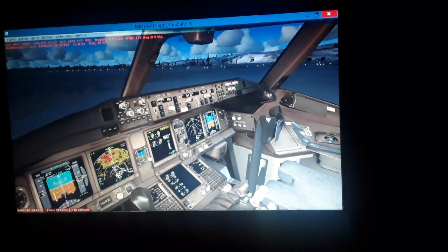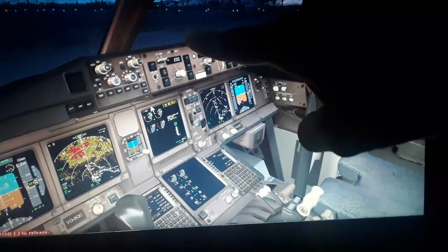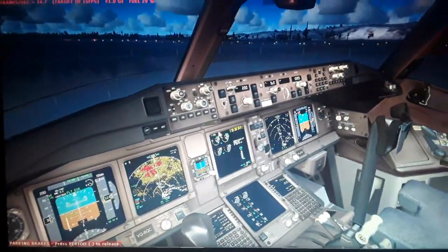Also, this is gonna give the data to the autopilot flight director system panel for the LNAV and the VNAV functions of the autopilot and flight director system panel. You can see here these two switches take all the data from the flight management computer for flying the aircraft in the automatic mode, using this data for the later vertical navigation of the aircraft. We're gonna follow this purple line in the navigation display with the STAR waypoint.